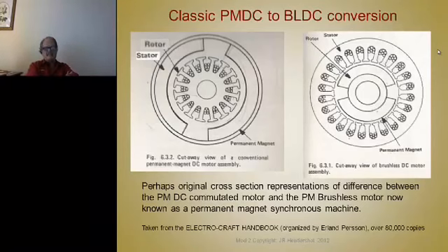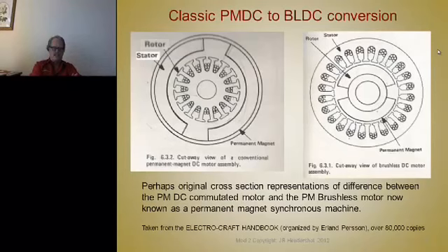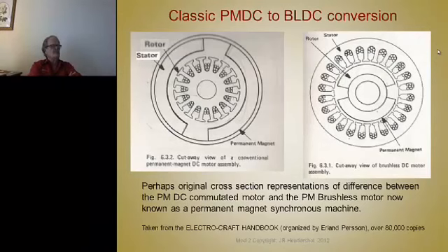In fact, what you concentrated on when you designed these brushless motors in those days was to get a high winding factor, high efficiency, and low losses and good performance, and good torque versus amp. You wanted to keep the losses as low as possible, and you didn't really care all that much what the back EMF looked like. It wasn't important.